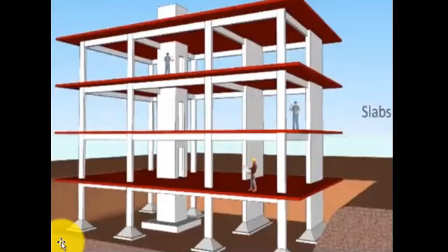The advantages of a solid slab are, number one, it is easy to construct. It doesn't take much effort to construct it. Number two, the material used for the formwork is cheap. The material is usually marine board or any kind of timber you wish to use, so it is not too expensive and it is easy to get, therefore it is cheap. Number three, the construction time is fast. And number four, it is economical.